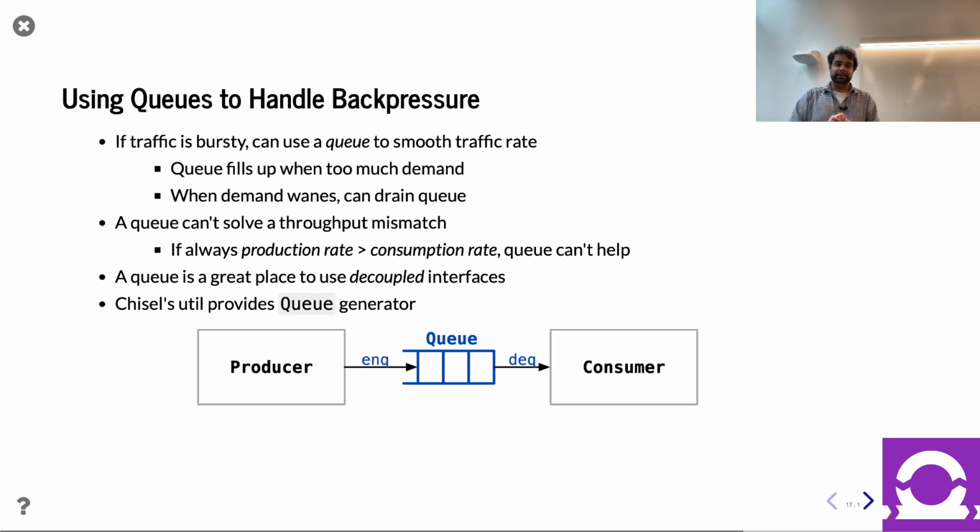And the reason why we're talking about queuing today is that there's a queue in the Chisel Standard Library, which is really helpful. It's a FIFO, but the way it talks to the outside world is with this decoupled interface. This interface we just covered is something handy in Chisel. You get access to a lot of stuff. And we know that behind the scenes, each of these decoupled interfaces is going to be bits, ready, valid. So this queue is actually 6 different signals coming in and out of it, 3 for each side. But using decoupled is actually not quite as complicated as it sounds.